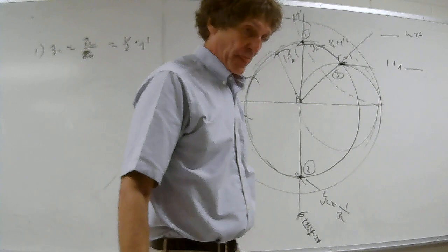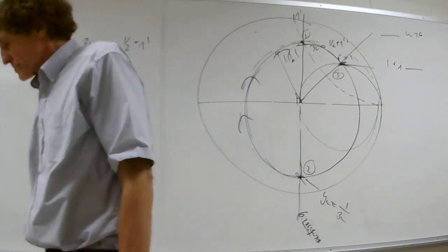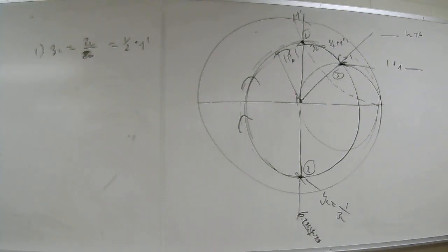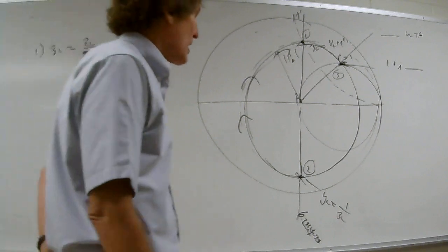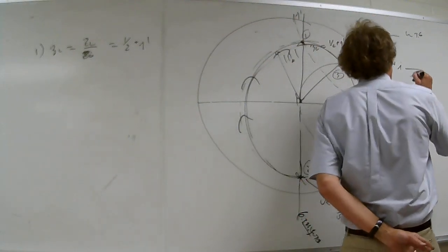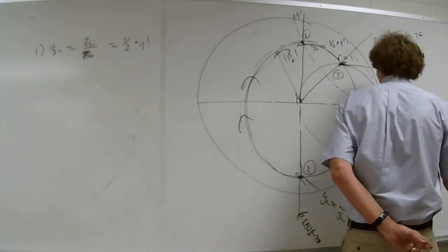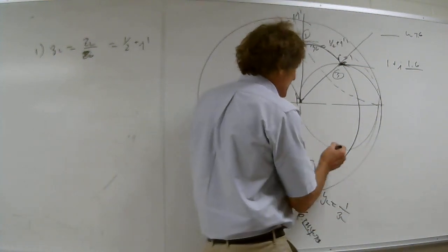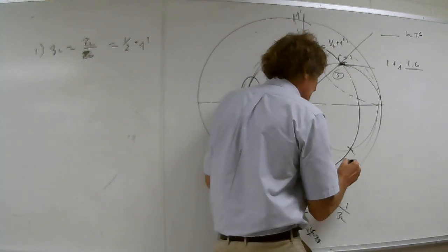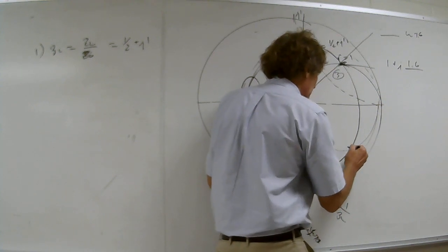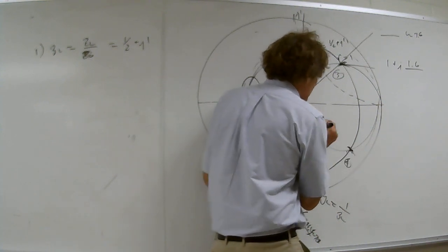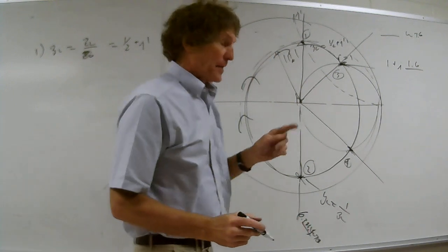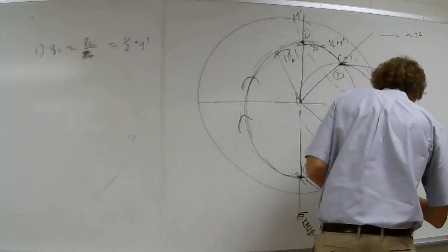Go ahead. Oh, you want the J value? It's going to be J 1.6. All right. Now, while I'm at it, and you guys are giving me that, shoot a line right through here where it intersects here. That's 0.3, this is 0.4. And shoot a line through there, and then give me the wavelengths towards generator here.